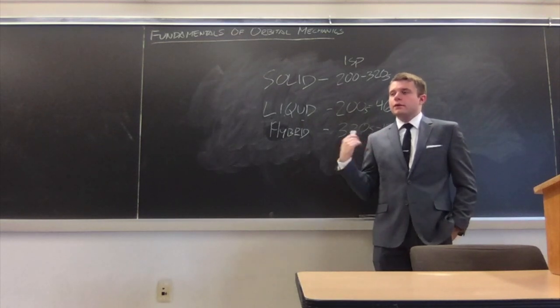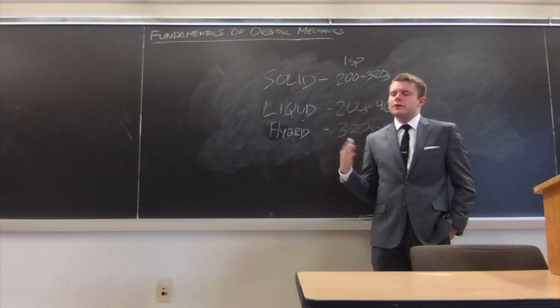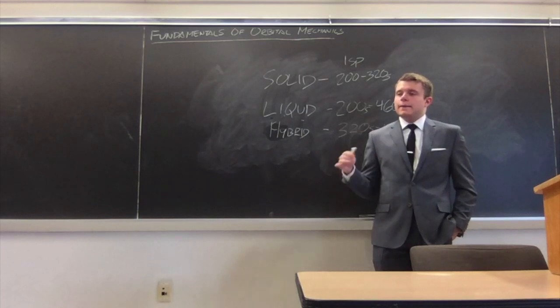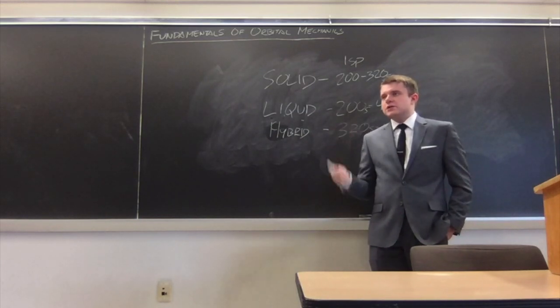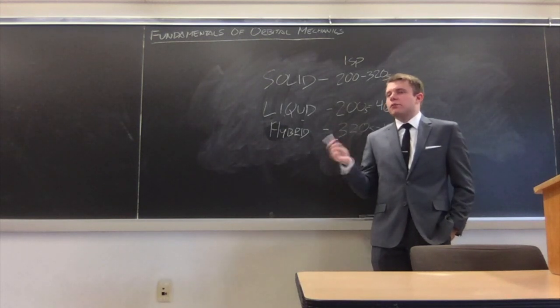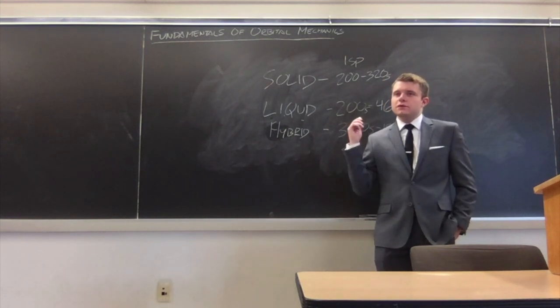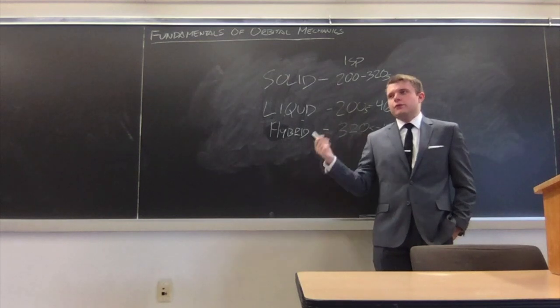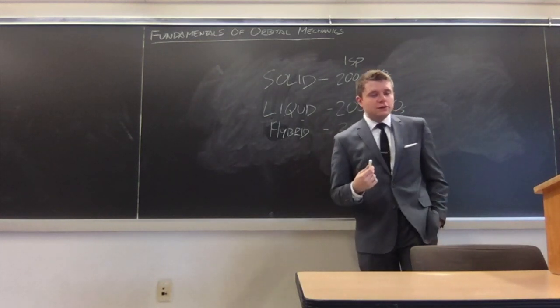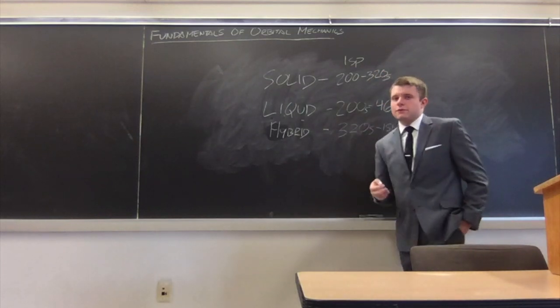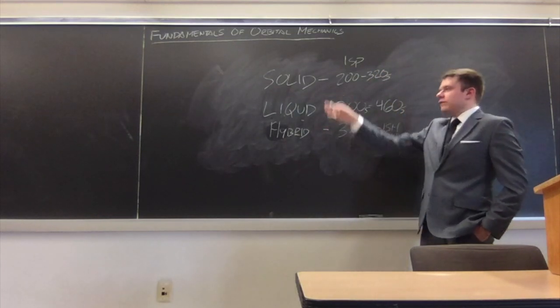I think it was specifically unsymmetrical dimethylhydrazine or Aerozine 50, I always get those mixed up, and nitric acid. They had to change the stage out if it sat on the pad fueled for more than 20 days, because it would dissolve and corrode the internals of that stage so badly that they would actually have to change it. So just a little footnote in the grand scheme of what these considerations are made for.